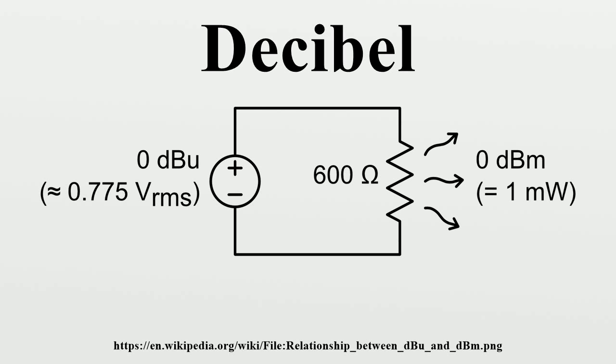In 1924, Bell Telephone Laboratories received favorable response to a new unit definition among members of the International Advisory Committee on Long-Distance Telephony in Europe and replaced the MSC with the transmission unit. 1 TU was defined such that the number of TUs was 10 times the base 10 logarithm of the ratio of measured power to a reference power level. The definition was conveniently chosen such that 1 TU approximated 1 MSC. Specifically, 1 MSC was 1.0562 TU.